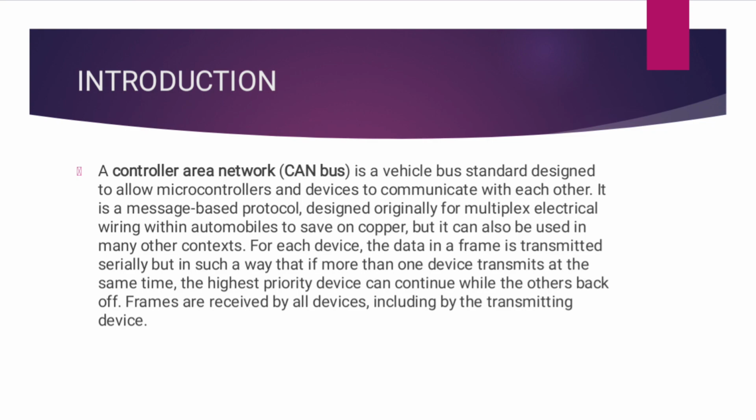For each device, the data in a frame is transmitted serially, but in such a way that if more than one device transmits at the same time, the highest priority device can continue while the others back off.